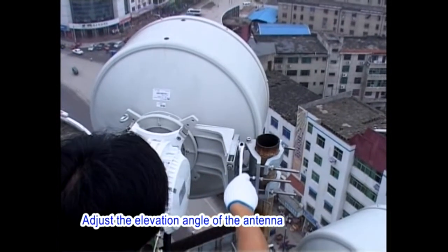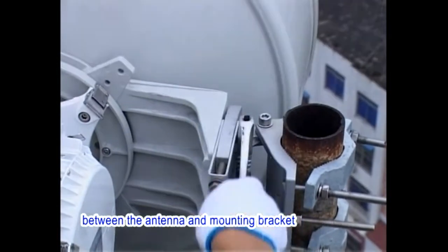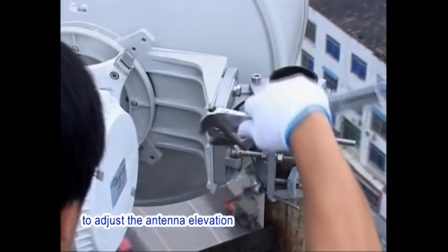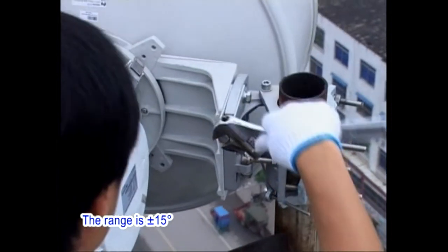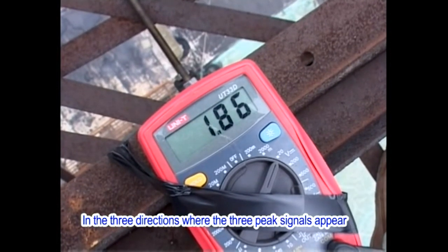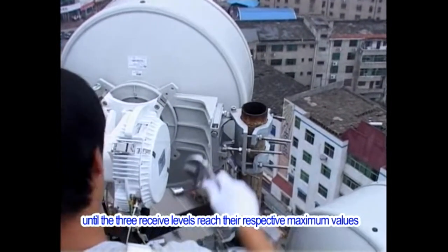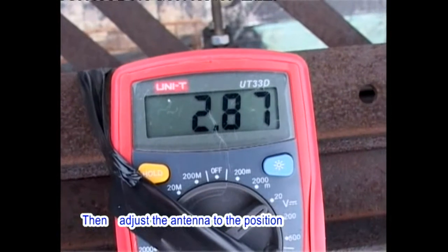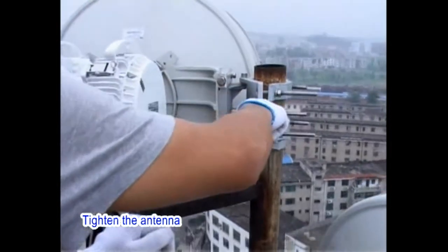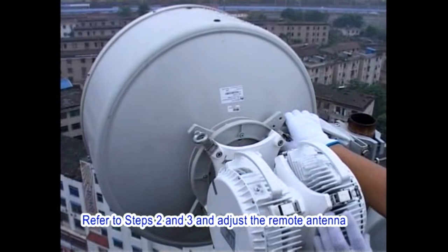3. Adjust the elevation angle of the antenna. Properly loosen top and bottom connection bolts between the antenna and the mounting bracket. Rotate the elevation adjusting bolts to adjust the antenna elevation. The range is -15 degrees to +15 degrees. In the 3 directions where the 3 peak signals appear, adjust the elevation angle of the antenna until the 3 receive levels reach their respective maximum values. Then adjust the antenna to the position where the receive level is the highest of the 3. Tighten the antenna. When you tighten the antenna, ensure that the receive level remains at the maximum value. 4.